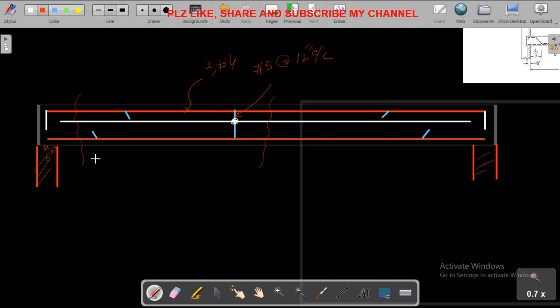Here I'm cutting this bar at a distance of Ln by 20, right? So my clear span is 25 feet. So this will be 25 times 12 divided by 20. It will give me 15 inches, right?